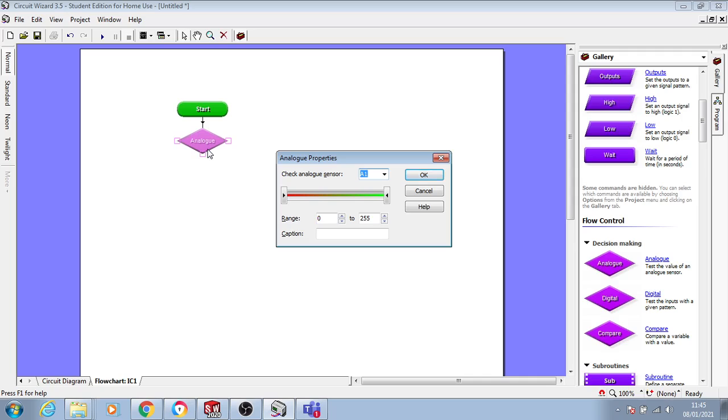You'll quite often see that in electronics. And what that's done is split that 0 to 5 volts into the range of the digital range. So in this case, however many bits it is, it's 256 steps. So it will measure that 0 to 5 volts in that range. And you can just calibrate the range here.